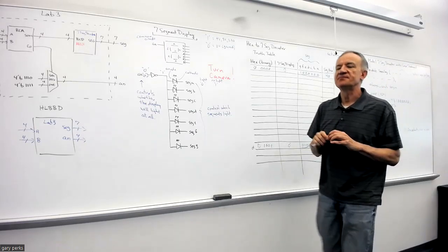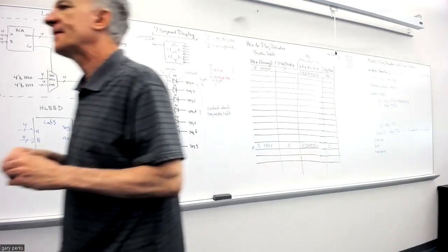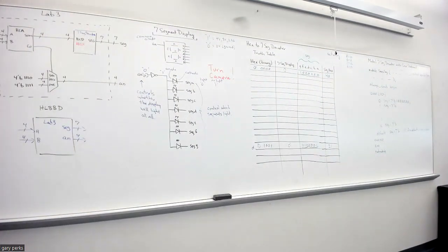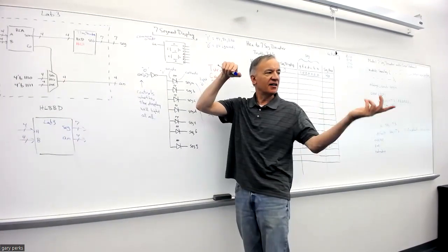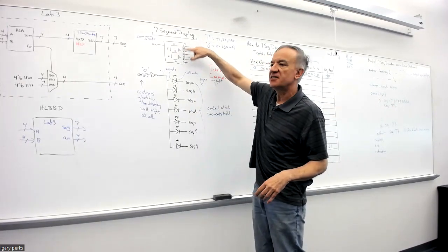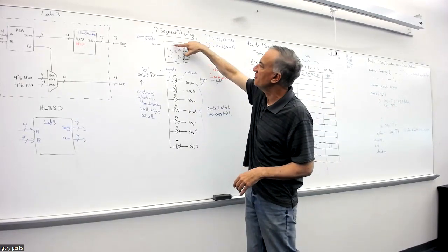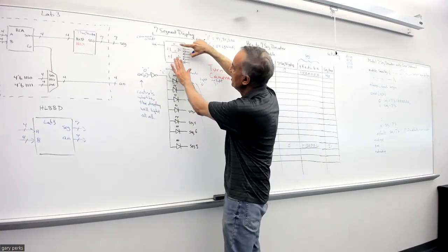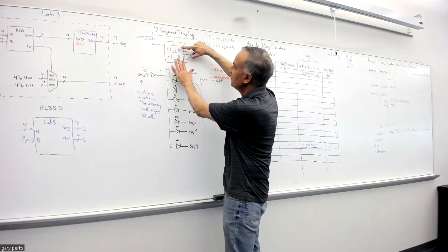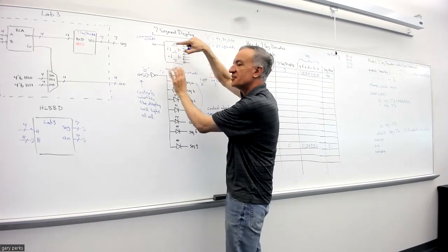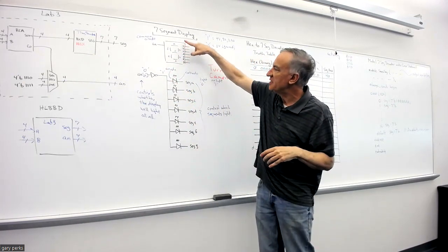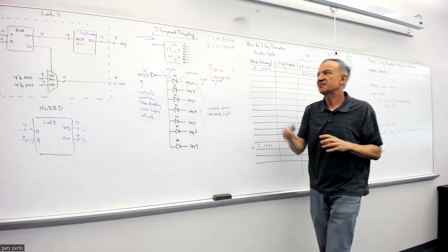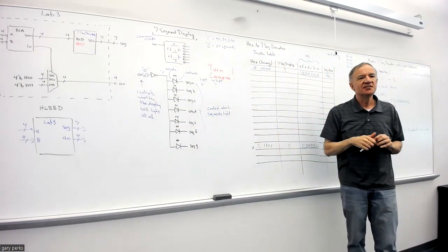There's a question: when you display a one on the 7-segment display, is it on the right side or the left side? Is it B and C, or A? Yeah, I think you asked that question, but yes, it's BC. You want BC, only because when you do a 3, it's going to be referenced over here. So if the one's over there, it kind of looks funny. I understand the question, but I think most people would do BC, just because it lines up with the other numbers.